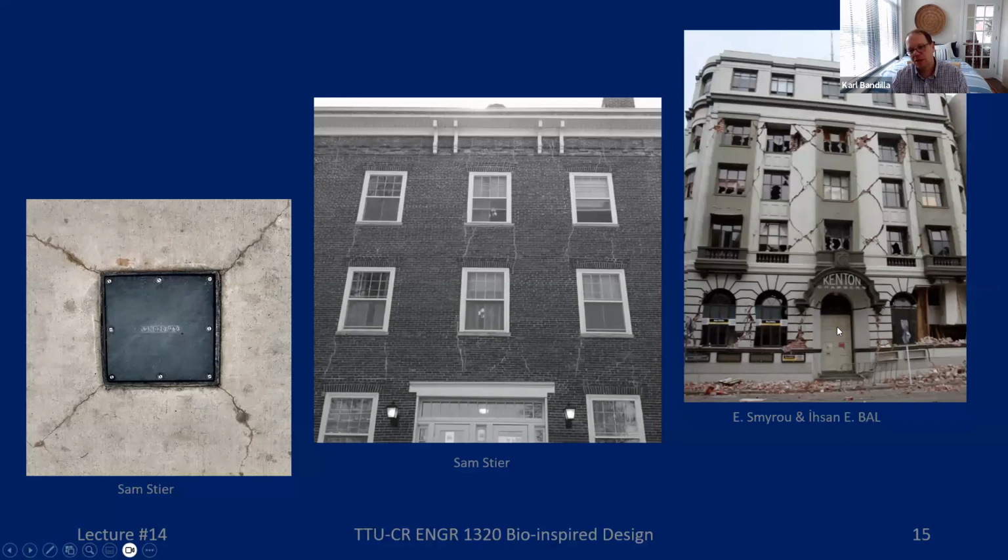And of course, this one here is after an earthquake, and you can see that the cracks all started forming at the corners of the windows. They don't just crack in the middle. I mean, they cracked all the way across, but the original cracks all happened there. And that basically means that happened because the stresses there were the highest, and that's where it fails first.